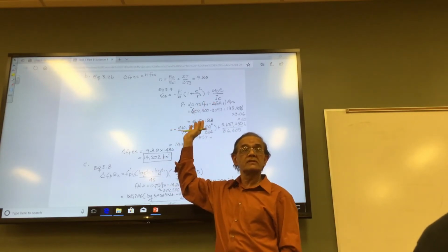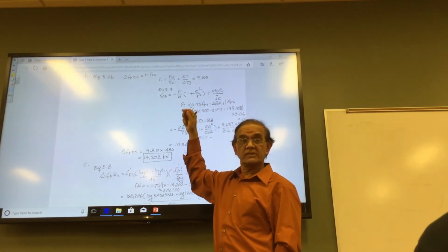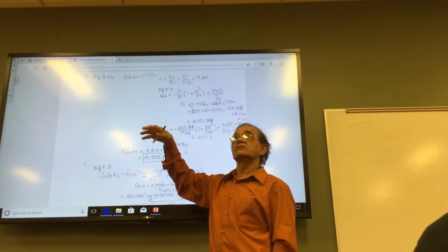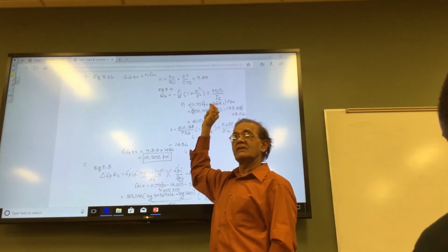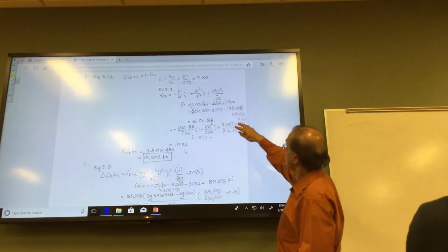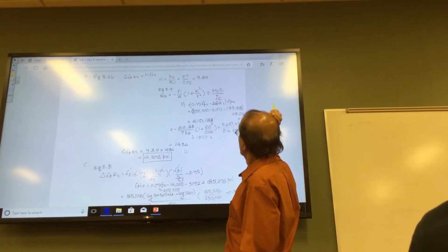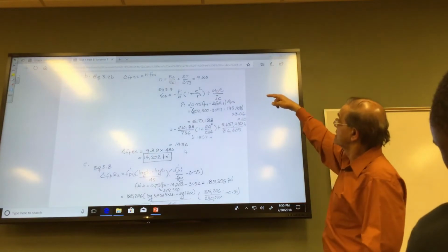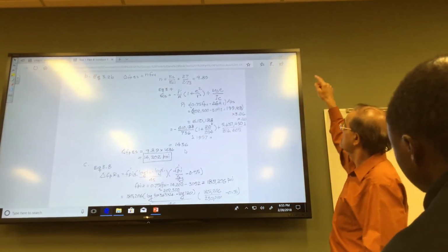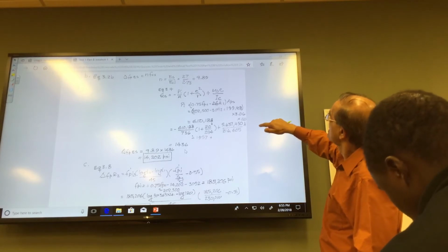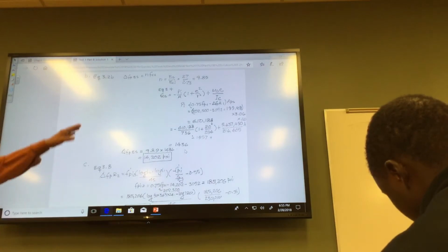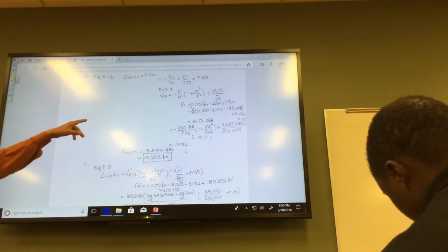2.73 is given to you, right? And if somebody calculated E based on the given compressive strength at the time of transfer, that's okay too. Because it was given doesn't mean you can't use the formula. If you use the formula, you'll get a slightly different answer. But it comes out more than 2.73, by the way, if you use the formula for ECI at the top of this page. So nothing extraordinary there. This is from chapter 1, basically the FCS calculation for the dead load, because dead load is applied right away. You don't have to wait, so at 5 days you apply the dead load.